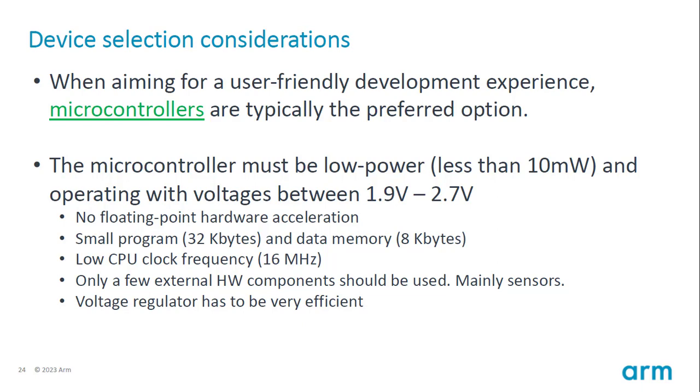When you build something like that, you also need to consider that in your system, everything will contribute to the power consumption. It's not just the microcontroller, also the sensors and other things. So keep it at minimum, do not put other items on the board.